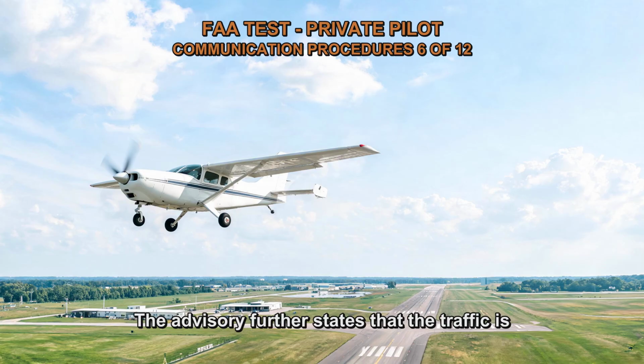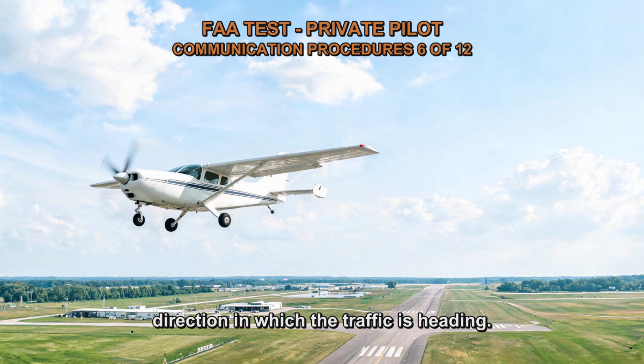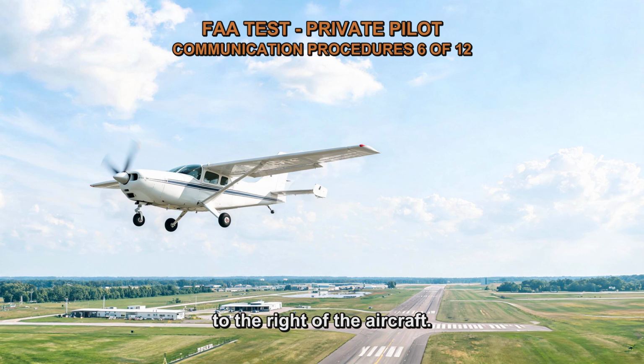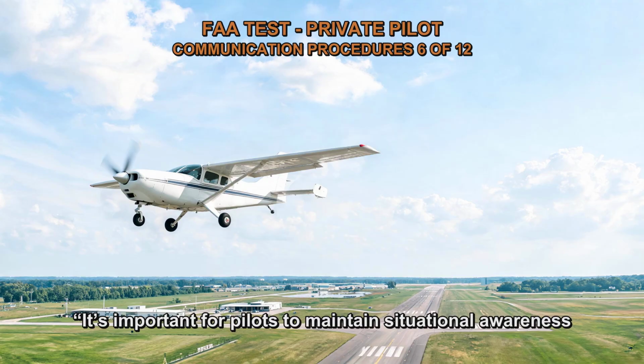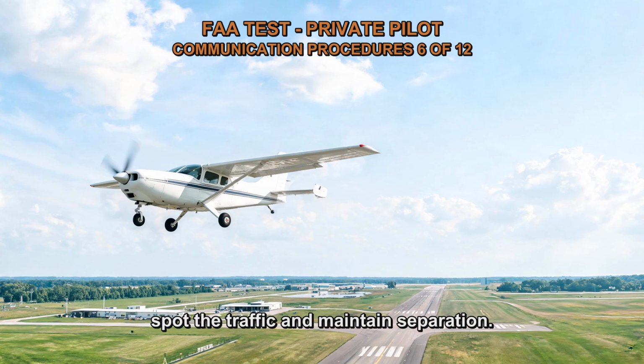The advisory further states that the traffic is 5 miles away and northbound, indicating the general direction in which the traffic is heading. To locate the traffic, the pilot should visually scan the area between directly ahead and 90 degrees to the right of the aircraft. This corresponds to option C. It's important for pilots to maintain situational awareness and visually scan the designated area to effectively spot the traffic and maintain separation.